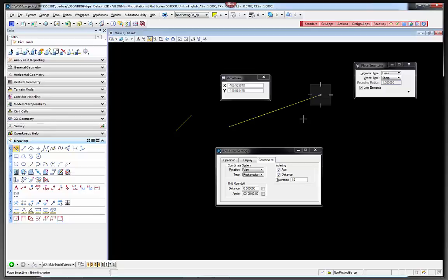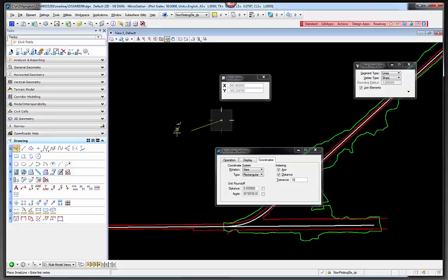Some of you may be familiar with it. You may not be. In this case, I'm in a rotated view. Notice that my compass, or my actual cursor there, is oriented by view. So if I were to draw a line, I could snap to these different views this way. And if I want to do a polar, I can switch it from rectangular to polar, and now I can set an angular lock here and a distance that way. And this is the normal sort of components.